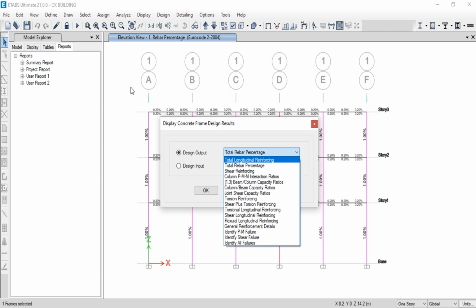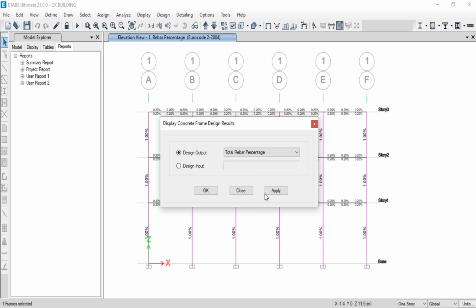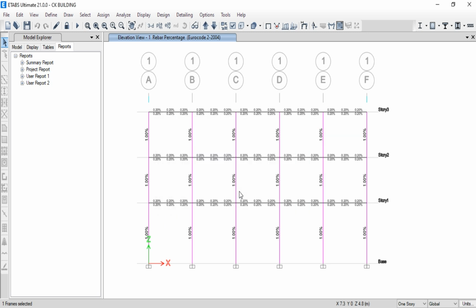So in order to resize the components, you just need to unlock the model and then redefine column and beam sizes according to the codes, using the rule of thumb according to the sizes of elements to be used. Then you analyze, run the model, then again carry out a concrete design check.